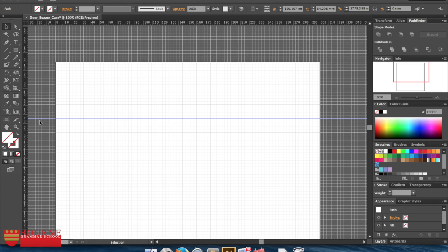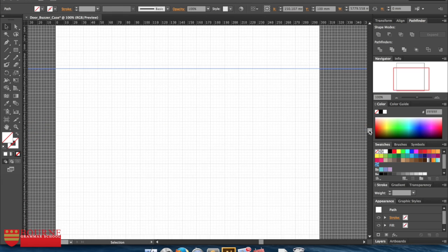Now it's a horizontal guide, absolutely horizontal, so its X coordinate isn't going to make much difference. I can make the X coordinate whatever I like, and it's not going to move the guide. But the Y coordinate here is quite important. So let me move that to 100 mil, and we can see that my guide has dropped down here. So my guide's now on 100 mil.